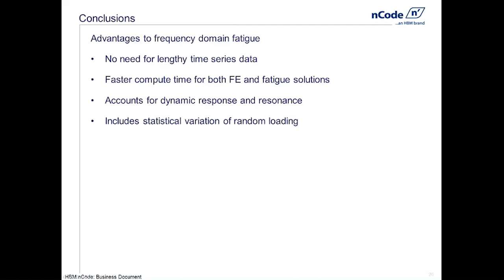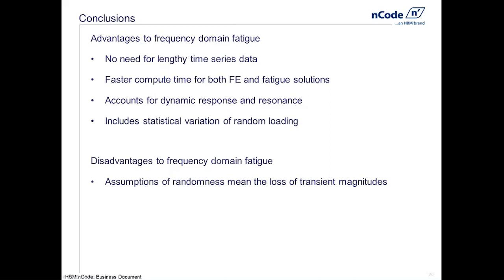Now, this all sounds very good. There are some great reasons to use vibration fatigue, but just keep in mind the downsides: in converting from the time domain to the frequency domain, we lose transient magnitudes. So we're looking at either peak amplitudes in the frequency domain or average amplitudes in the frequency domain.